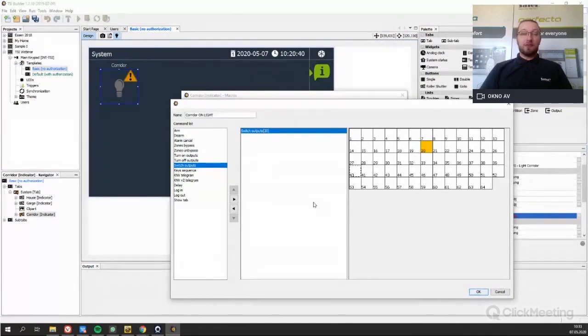If you are, for example, combining 4 different outputs, or 2 even, and if their status could be different than the other, like you have scenarios that you can control every single light separately, but if you want to turn on the scenario and you want to press one button to turn it all on, switch output will not be the best idea, because if the one is on, then this one will turn off and the other will turn on.